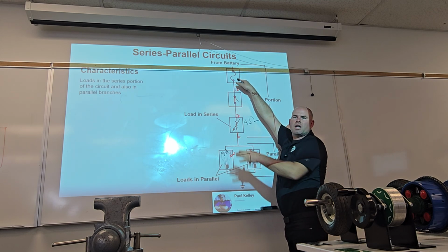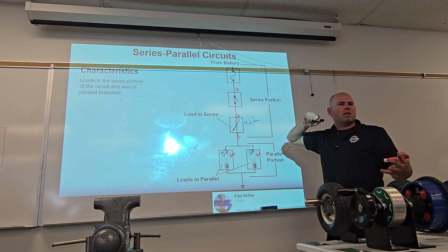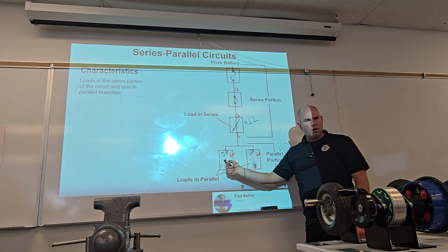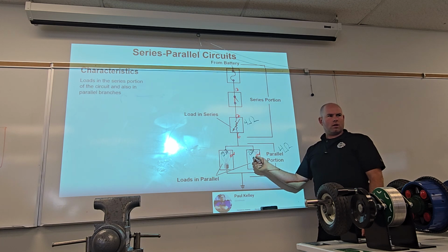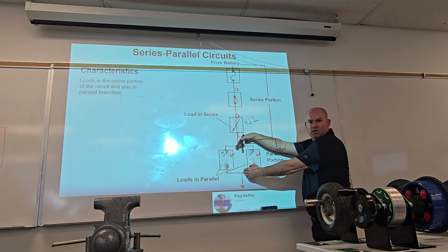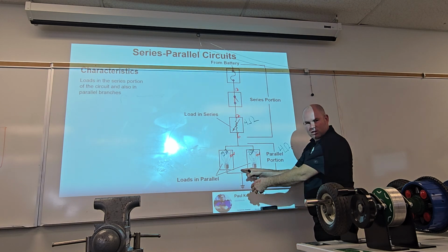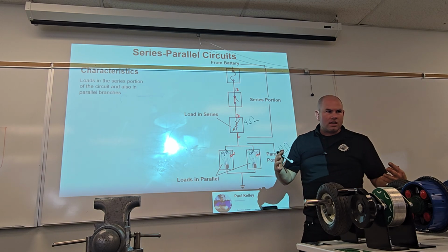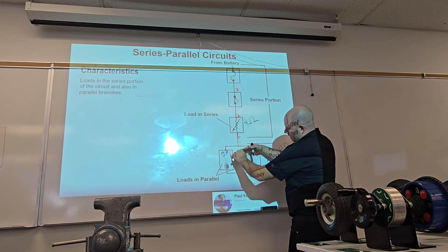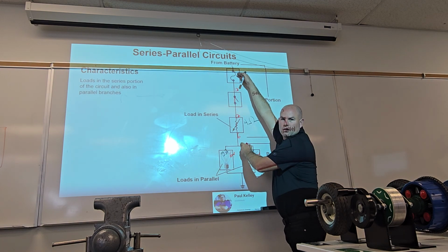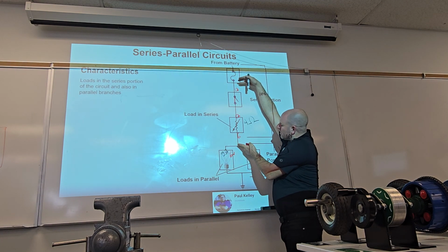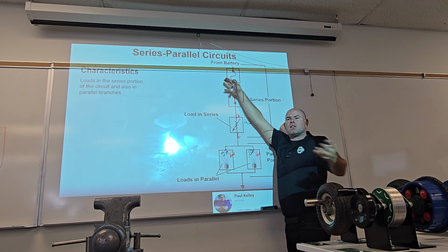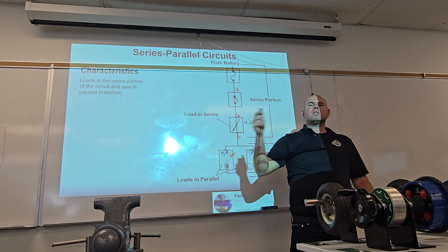Make sense? So once again, you're going to evaluate the circuit. Let's say the instrument panel lights work, but the radio lights don't work, then you're troubleshooting here. You're troubleshooting the circuit that's specific to the radio lights. But if all the lights are too dim, I don't really care about right here. I care about right here. At which point, if you're diagnosing between here and here, what type of circuit is it? Series. Exactly. So once again, you're diagnosing a series circuit.